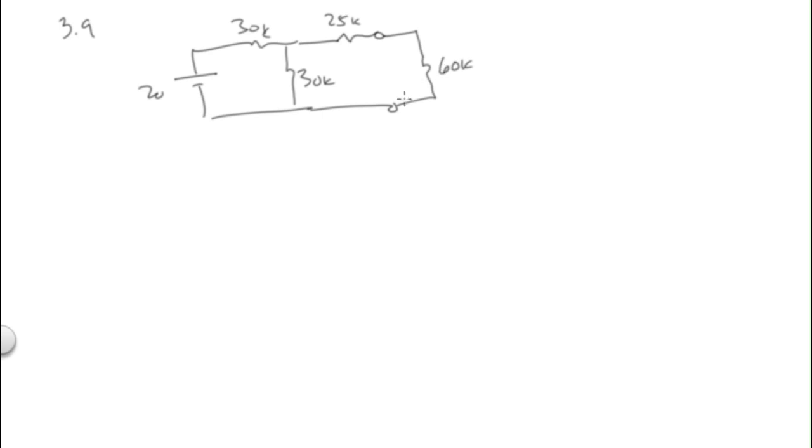So if it's open circuit, what would be the voltage across it? The open circuit V AB is equal to 10 volts. We're going to ask the same question: if you put the resistor across it, what would it be? But if you remember, this would drop from 10 volts. 30 and 30 is 15, plus 20 is 40. This is the dangling resistor, remember that. So now we want to add 40 plus 60.